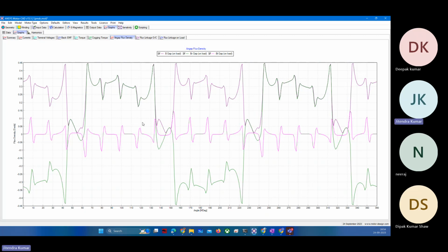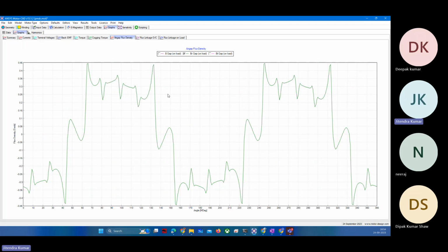In the space domain, you have provided constant DC, but in the time domain you are still receiving fluctuating waveforms. So your air gap flux density is not DC. This air gap flux density waveform, are you able to see it? What would you say to these kinds of signals?